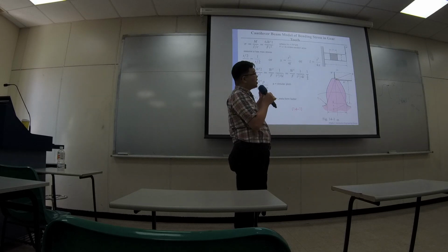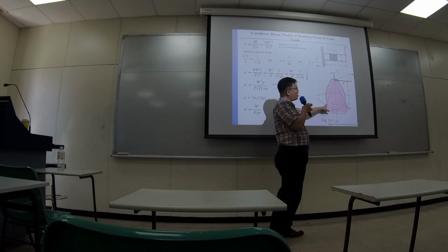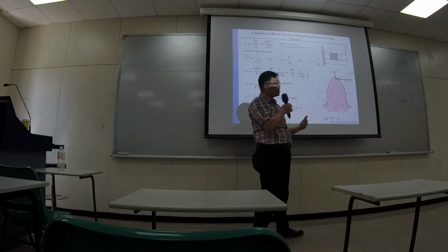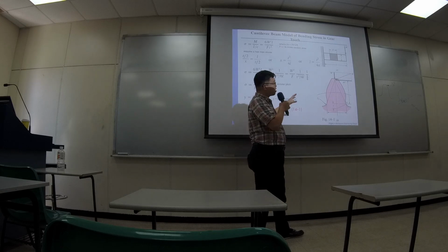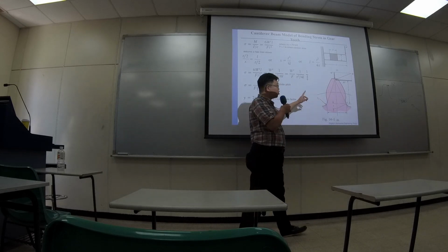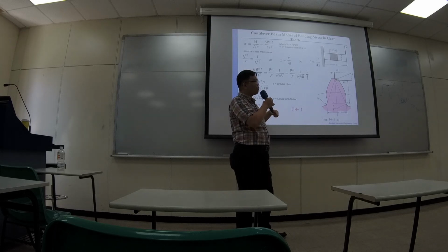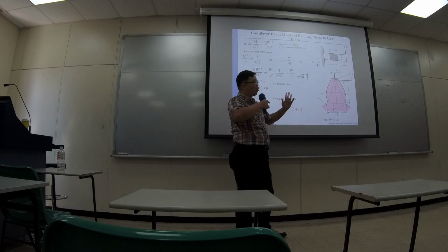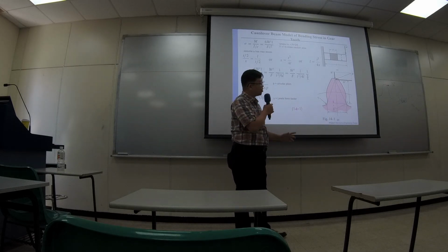So basically, he modeled the tooth profile in a more general way. If you use whatever he introduced, convert all dimensions into dimensionless, then you have a standard equation, one equation for all tooth design, but it's based on some kind of approximation.